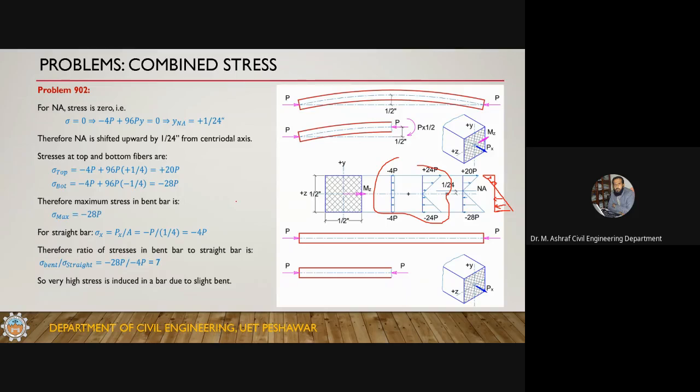During construction, there is a possibility that your formwork may move to one side. When it moves to one side, the stresses are higher at one side and lesser at the other side, and there is a possibility that the high stresses may exceed the strength of the material and there could be a failure.